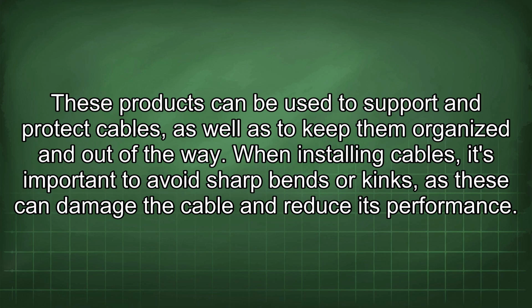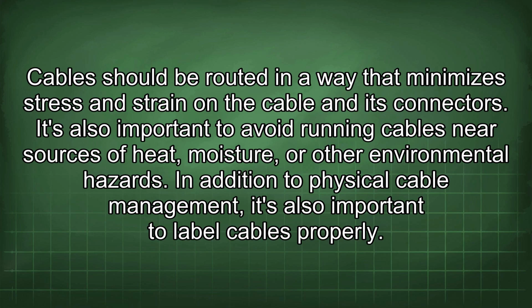When installing cables, it's important to avoid sharp ends or kinks, as these can damage the cable and reduce its performance. Cable should be routed in a way that minimizes stress and strain on the cable and its connectors. It's also important to avoid running cables near sources of heat, moisture, or other environmental hazards.